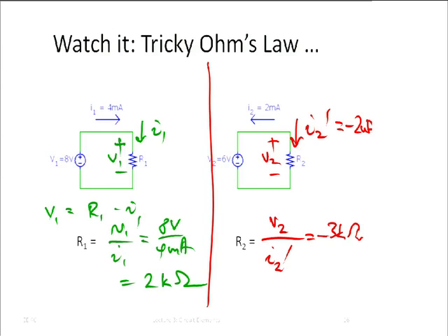Actually, it decays exponentially. Why does it stop? Well, because it dissipates power. You can model this dissipation by saying this crystal that moves, or that grandfather clock that moves, looks like a resistor that dissipates power. A totally normal positive resistor. We don't want it, but nobody ever figured out how to make a clock that doesn't stop if you keep kicking it. Okay?